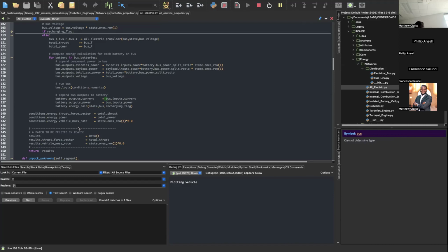The question came because let's say we have 2 battery packs, one a new battery pack and the other an older battery pack. And midway through the flight, one battery pack fails, like in terms of weight. So it needs to learn on its own that there is 0 voltage here and change the split ratio. That is more of a BMS issue.